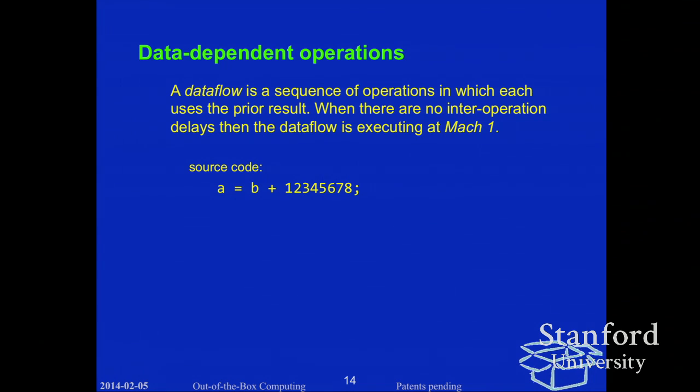We've got a big constant there that's much too big to be done as an immediate in an add operation. I'm assuming a load store architecture here, not something like an x86, where you have funny extensions and huge instructions that can carry big constants. But think of your typical RISC type instruction set. And the machine code of this is, well, you're going to have some kind of an operation that builds a constant for you.